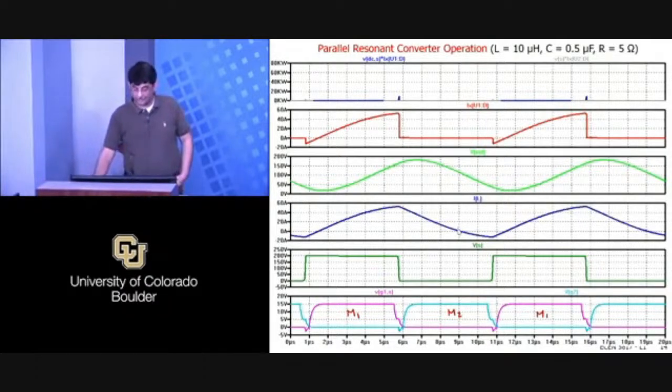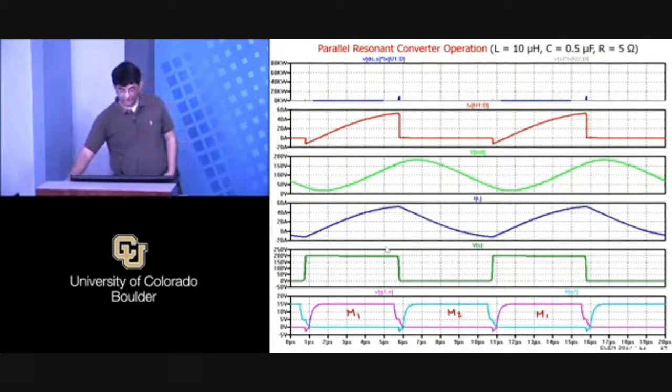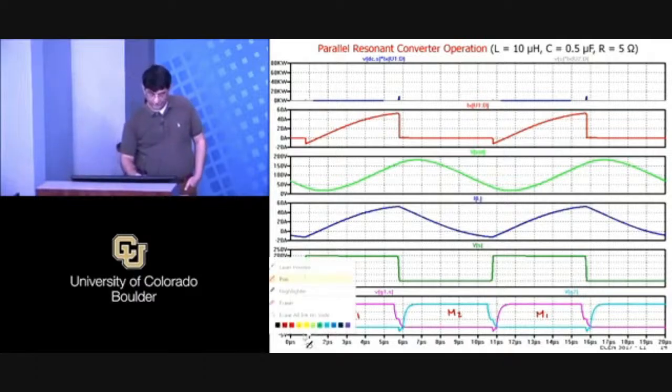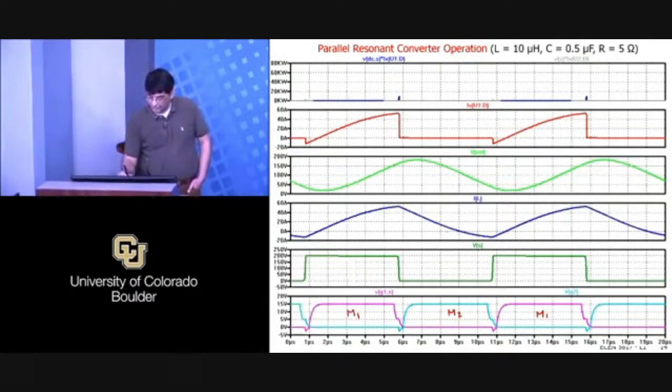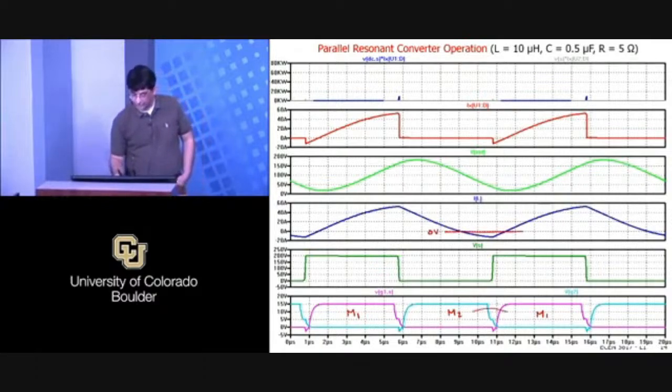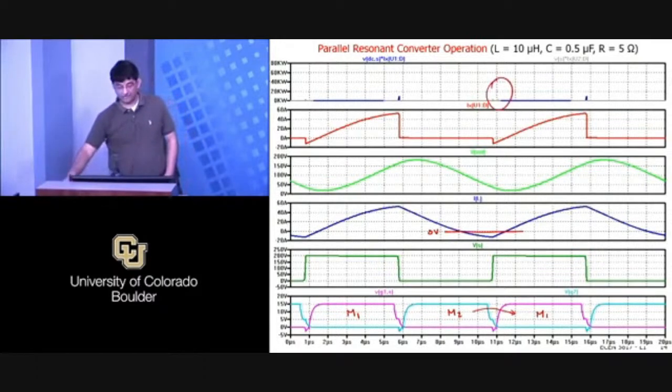And again, the key thing here is that I have negative current in the inductor at that transition. The transition from M2 to M1, which was the transition that troubled us, again has negative current, and so again that power loss is gone, right? Same phenomena, same everything, except waveforms are slightly different.